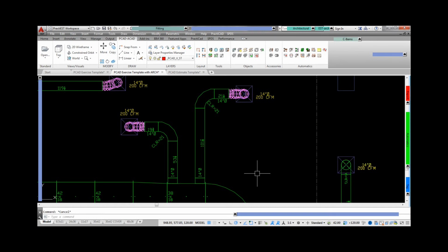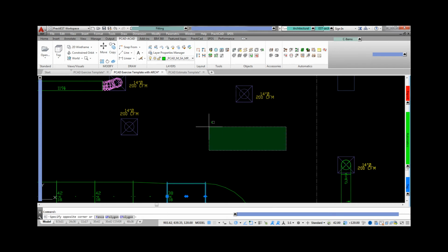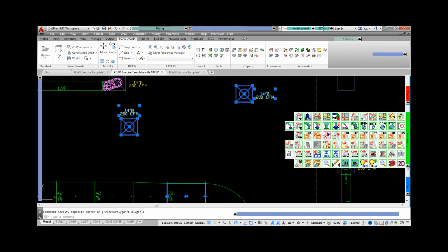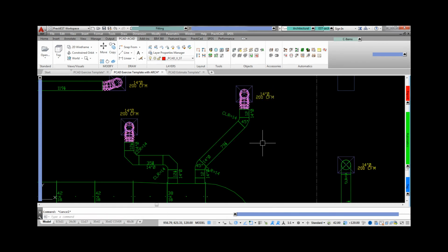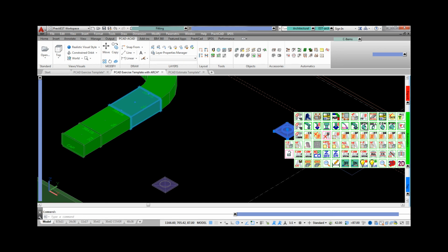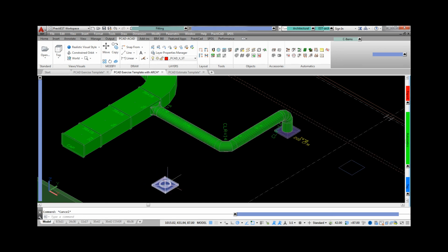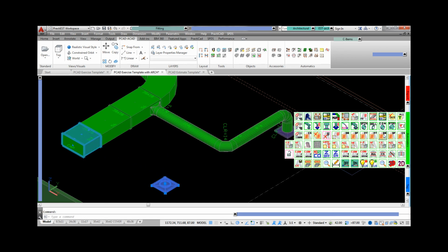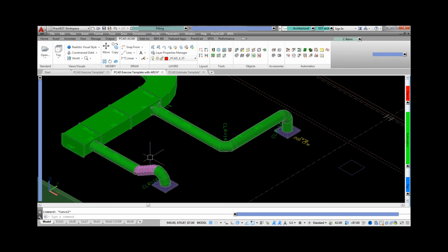In this next example, we're choosing between 2 choices. The first route's 1 turn at 90 degrees, the second route uses 2 turns with 45-degree elbows. If the engineer requires a hard pipe connection or doesn't allow for you to bend flex on the GRD, then simply adjust your route accordingly. Hard pipe options and options that require an elbow, no matter how far the drop, are available.